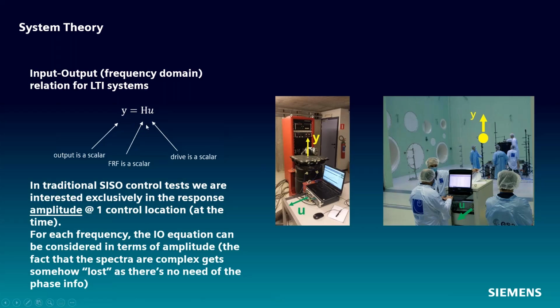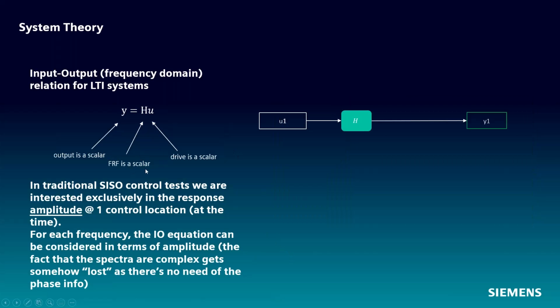And then you have this transfer function, or FRF, that you're able to deduce through some pretest analysis, and that's multiplied by this drive signal to get this output. What we're doing here is inverting this, multiplying by the control spectrum and figuring out, after some corrections, what our drive in voltage needs to be. These are scalar values, so the math is pretty straightforward.